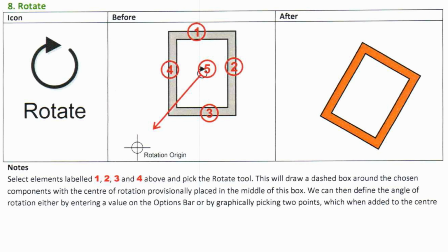Rotate tool, controlled angular transformation. Purpose: rotates selected elements around a defined center point. Useful for angled layouts, component orientation, and symmetrical adjustments. Workflow: 1. Select the elements to rotate. 2. Activate the Rotate tool from the Modify tab.